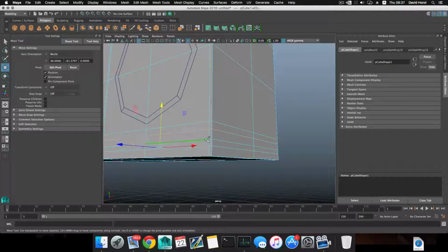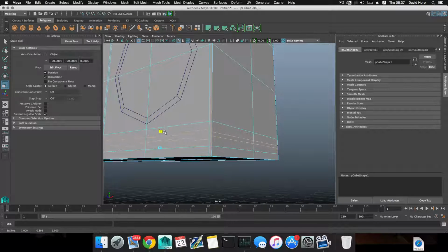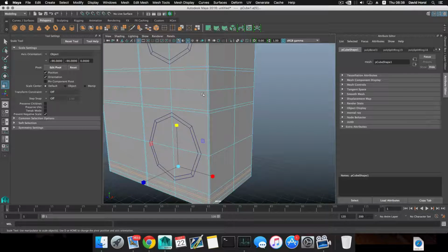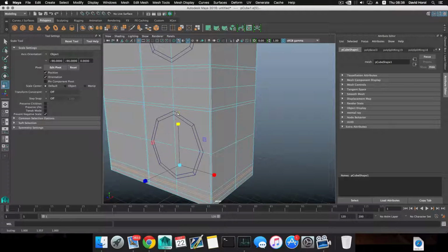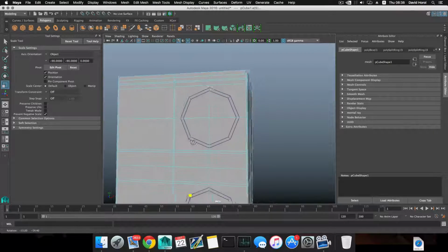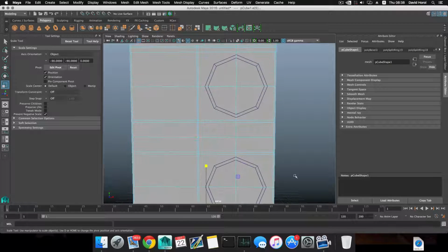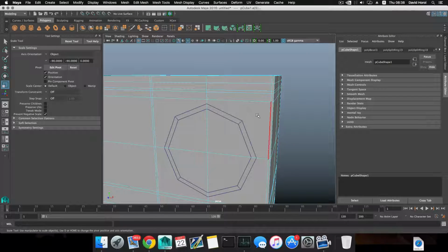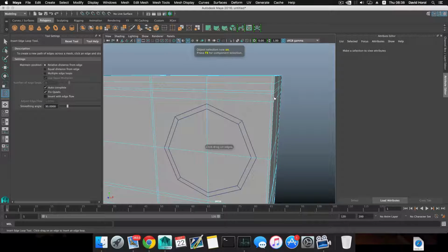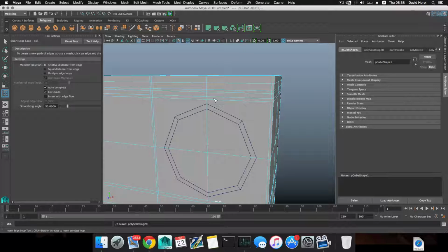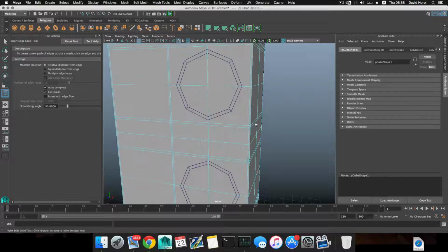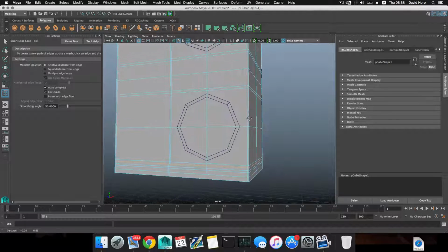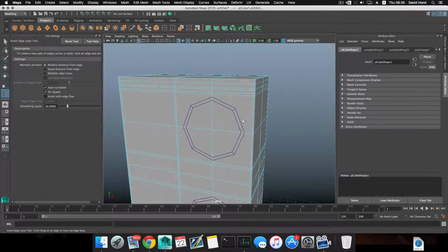I'm gonna double click on this one, shift double click on this one. I'm gonna bring them to about the same scale as I did with these two. Okay, it doesn't have to be accurate. If you go on making things accurate, you know the procedure, just like we did here. Delete, half cut, and replace with a duplicate one. I'm gonna make just one more supporting edge here, to contain this. I don't want this to be part of this, and I'm gonna do just one more edge here. You can create it by creating an edge loop with control right click.